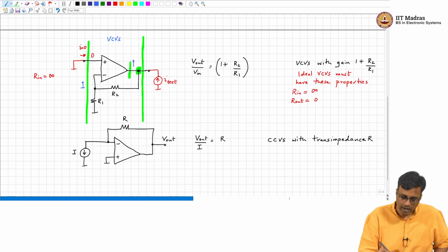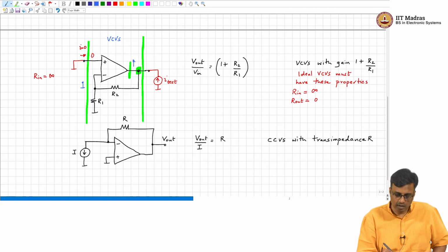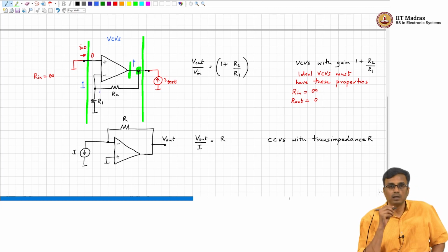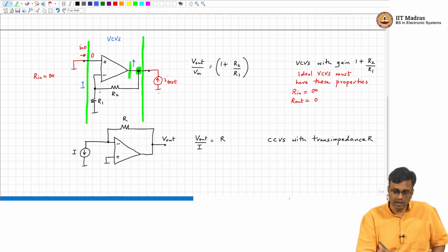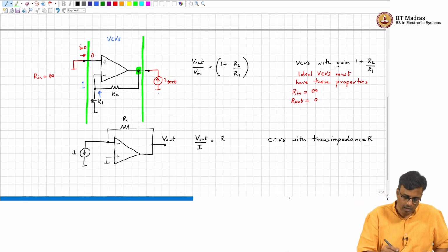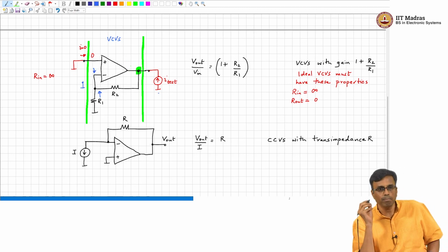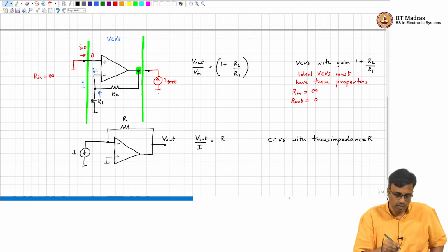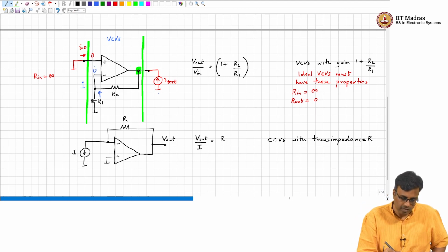we yank this side up, what happens to this voltage? This is a current source, right. So, if you yank this voltage up, what happens to this voltage? Increase. If that goes up, what happens to that voltage? Decreases. So, is there negative feedback? Yes. If there is negative feedback, what comment can you make about the potential at the inverting terminal of the op amp? This is 0, all right. So, what is the current flowing through R1?